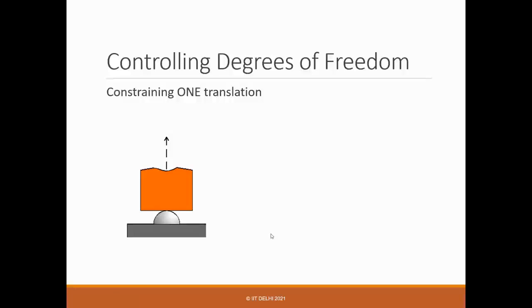And particularly when we design something based on constraint principles, I think it's very important to identify these contacts and also the constraint lines. And that will lead you to further analysis and whether you can say whether it's exact constraint design, whether it's under constraint. So if it's under constraint, then there might be some degrees of freedom left, and it should be able to move in those directions. But before you can do that, it's very important to identify these points. So either the contact point and then the constraint lines. So they are very basics.